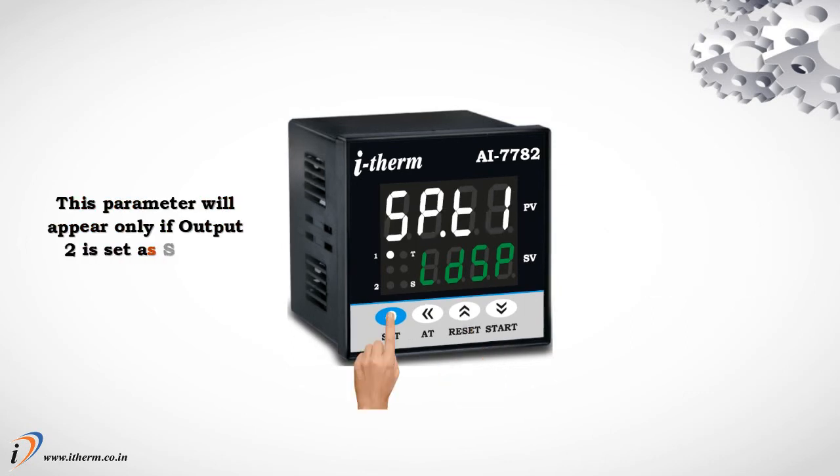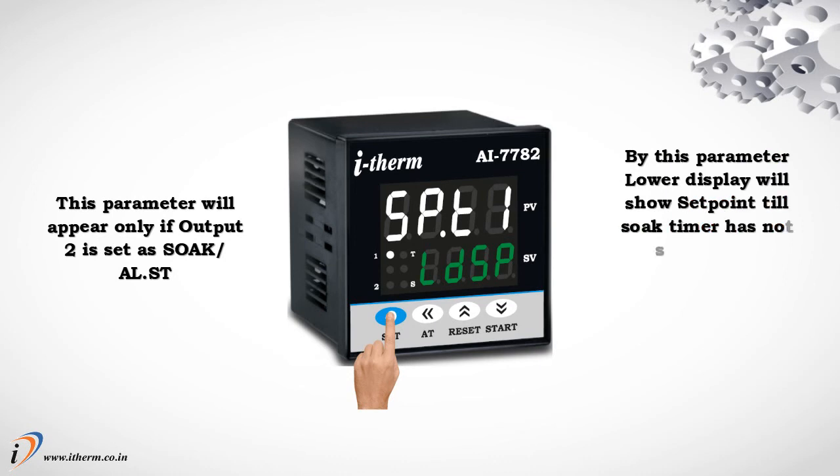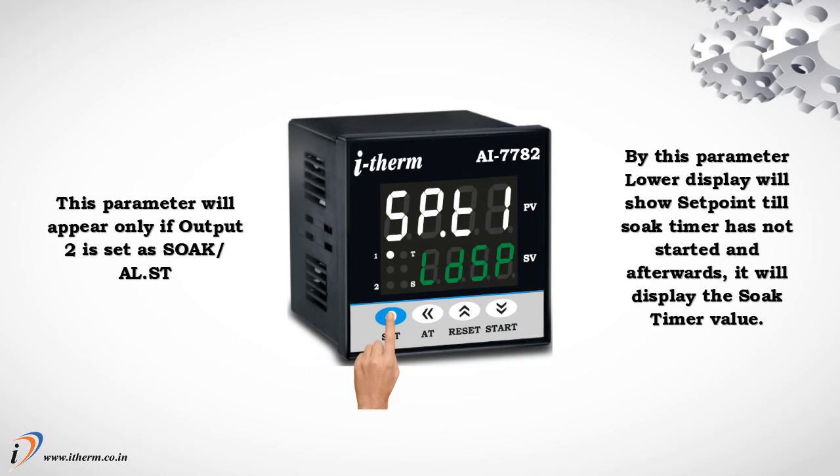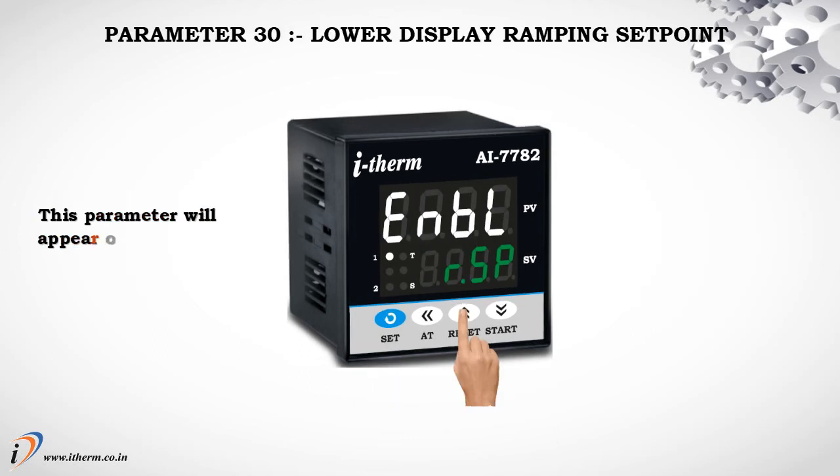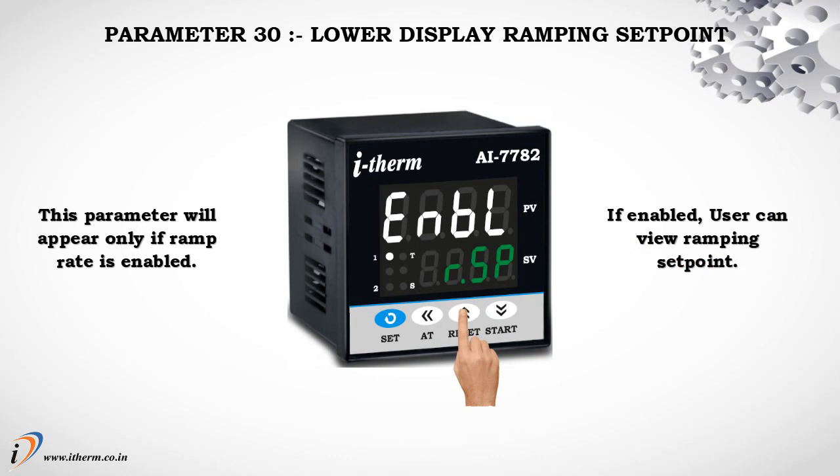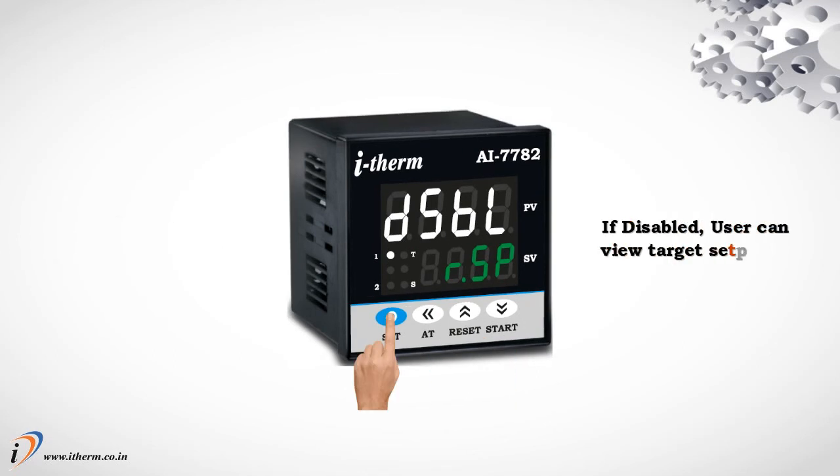This parameter will appear only if output 2 is set as soak, alarm soak time. By this parameter, the lower display will show the set point till the soak timer has not started, and afterwards it will display the soak timer value. Parameter 30, lower display ramping set point. This parameter will appear only if ramp rate is enabled. If enabled, the user can view the ramping set point. If disabled, the user can view the target set point.